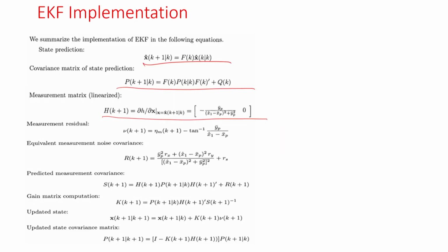How do you linearize? Again, you have to calculate what is known as the first order Taylor series linearization along with your x. So, first will be del h divided by del x, okay, and del h divided by del x dot, right. With respect to your state, you have to do linearization.